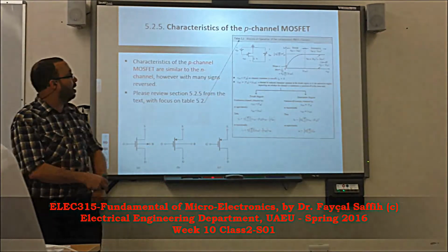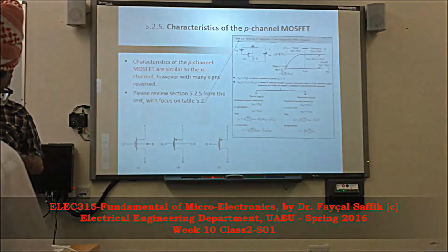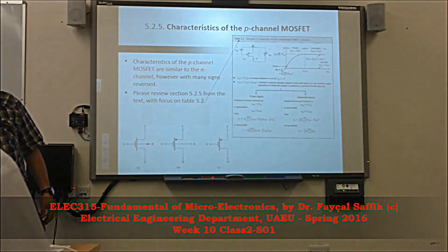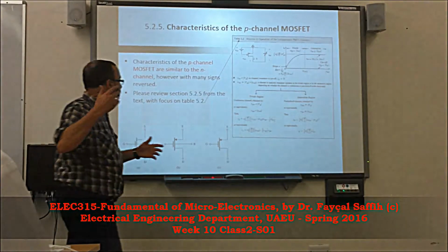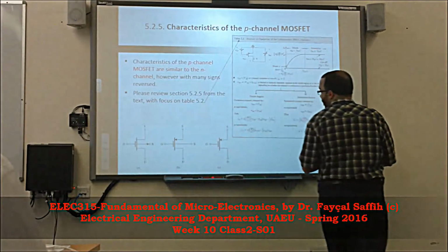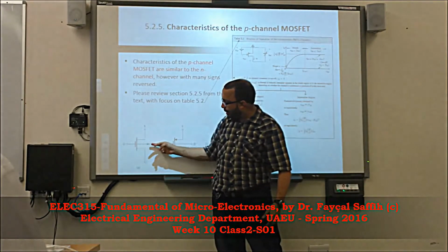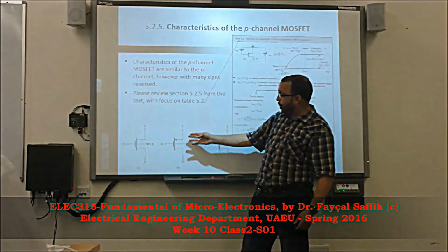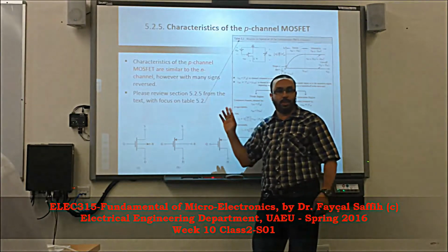Okay, great. Alright, back to the PMOS. So what we said in NMOS is just a symmetry, we get PMOS. Right? Replacing N by P, P by N, and reversing the currents and voltages and everything will be a done deal. So basically this is what we did last time. And remember for NMOS, the body arrow here was going in towards the gate. Now the current, as we said, is going from the source to the drain, not drain to the source.